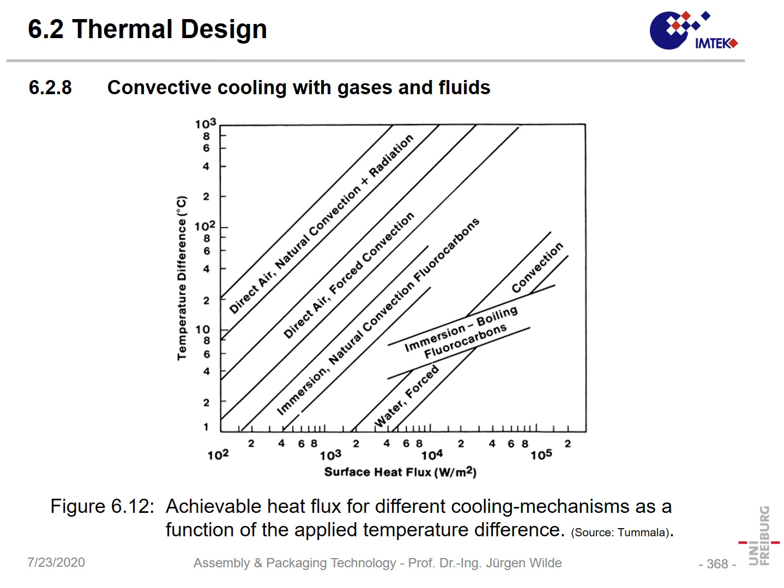And now for using air for cooling, natural convection plus radiation, we can say, okay, here we have proportionality, and in some way it is proportional for temperature differences from several Kelvin up to at least several hundred Kelvin. If we take forced air, it is very similar, but it's on a much higher level. So we have a linear behavior.